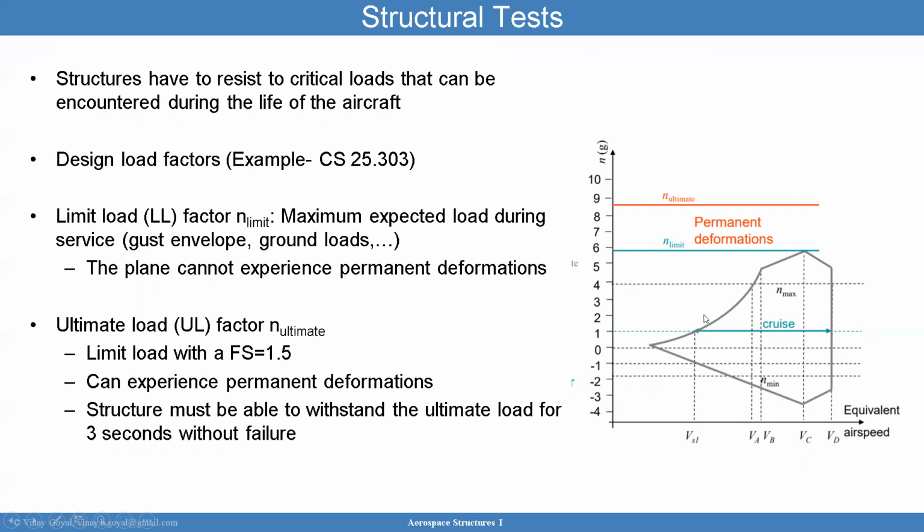Design load factors are basically really discussing the European standards, also the FAA FAR regulations, United States. The limit load factor and limit, here you can see here in this chart, is the maximum expected load during service, and that's this point right here, and that'll envelope any gust, any ground loads. The plane at these limit load conditions, when you apply the loading, cannot experience any permanent deformations. But above limit loads, permanent deformations could be acceptable.